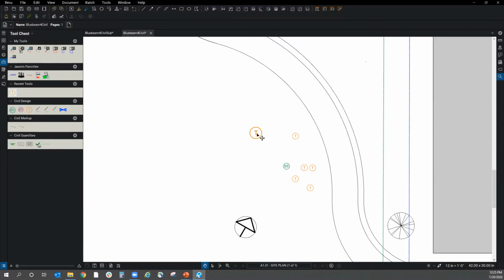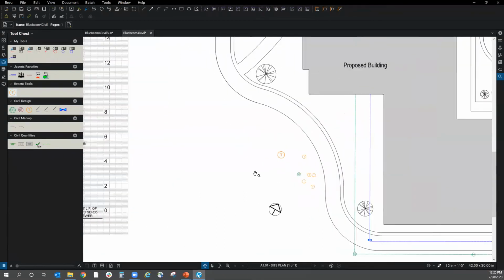Should sidebar a little bit there. There are two types of PDF files: raster PDFs and vector PDFs. Vector is anything that's created from the computer directly, right? So this was printed from CAD, and now it's a PDF. If it were printed to paper and then scanned, that becomes a raster PDF, all right? So using the snapshot method allows you to use any type of PDF.